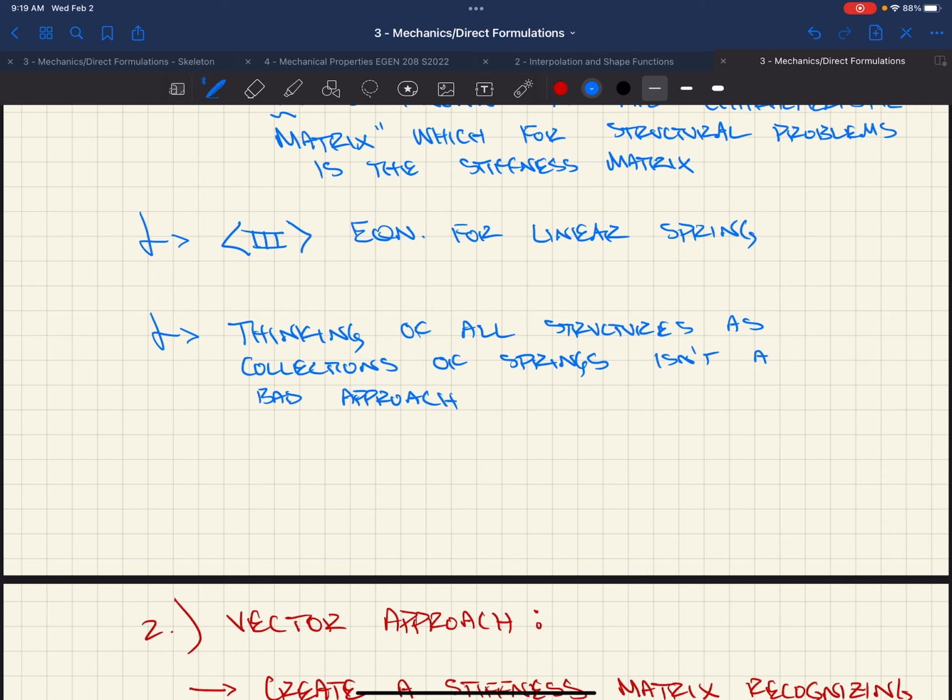So we were modeling, it was either Rendezvous Dining Pavilion or some other building, and it was making no sense. We were getting the reactions to design an ordinary brace frame, and our brace forces at the main floor level of the dining hall were more than at the ground level in the basement.